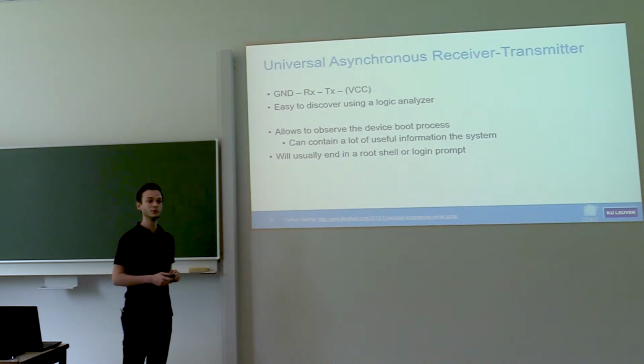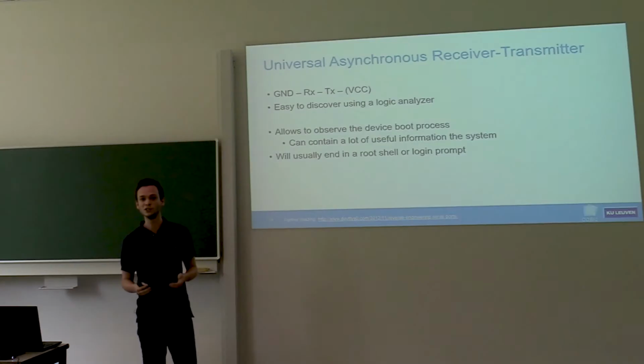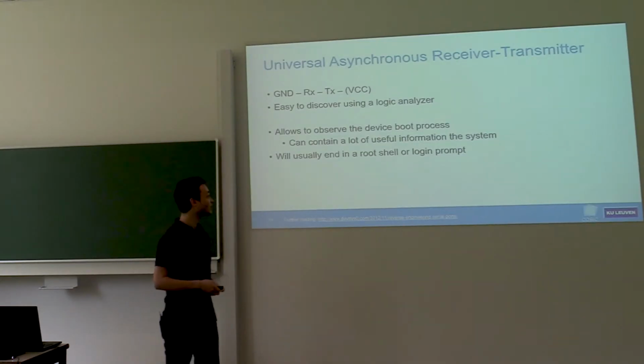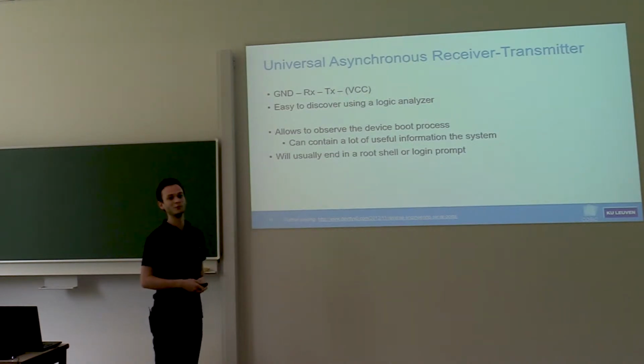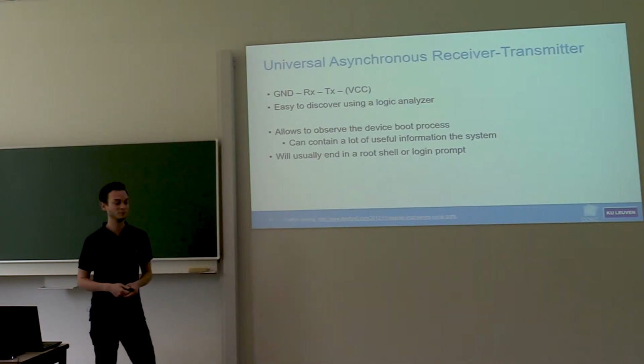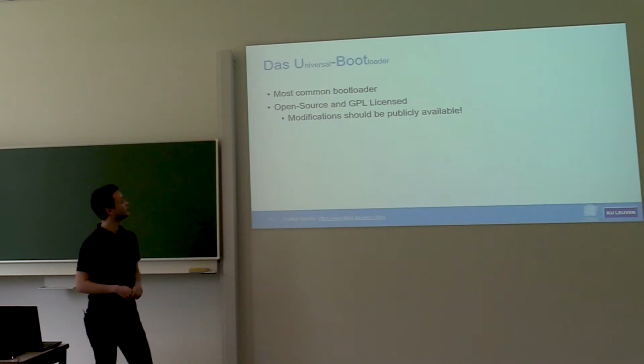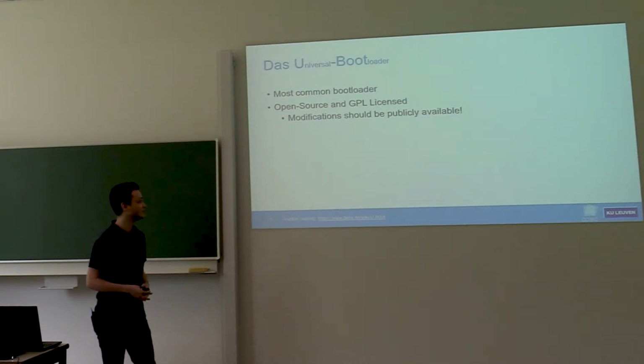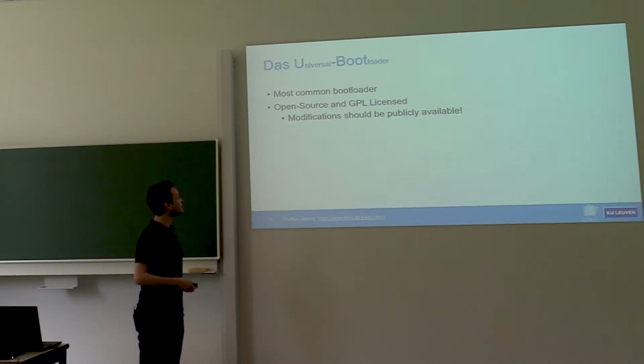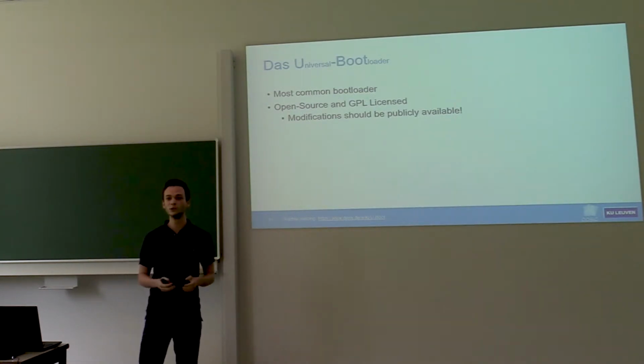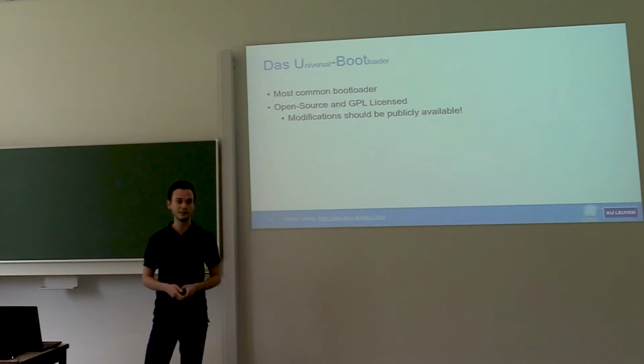Once the device is done booting, there's probably two scenarios that can happen. One is you end up with a root shell, and then you've already won. The other option is that you get a login prompt, and then we'll need to go to the next step. So what you'll often see when you boot one of these devices is the word U-boot, which stands for Das Universal Bootloader. And it's actually the most common bootloader that you will find in these devices.